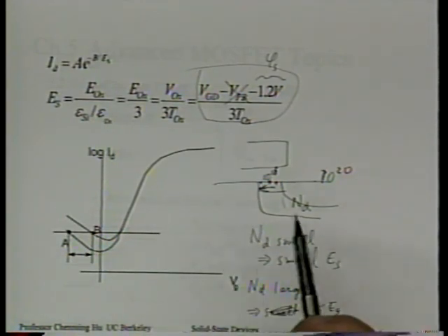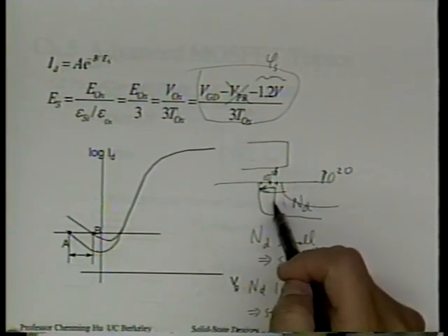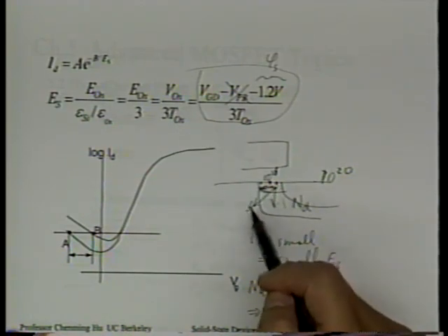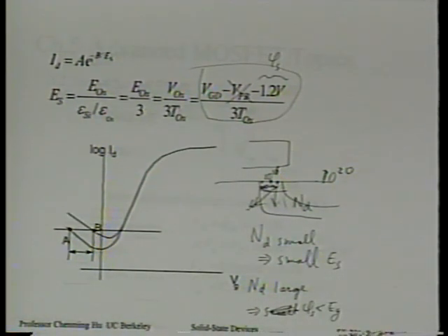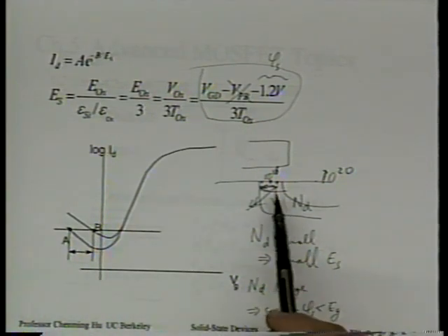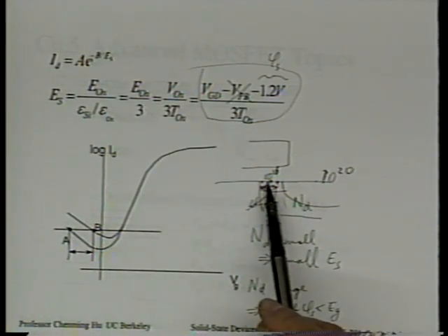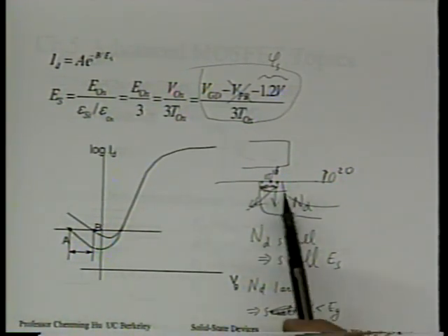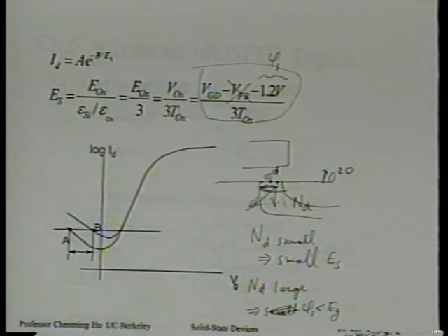And tunneling happens, doesn't matter which direction the field is. Vertical field, horizontal field, the carriers will just tunnel in the direction of the total field. So it's known that we cannot tolerate, for example, a very sharp, just arsenic junction. If we do that, GIDL is more severe, and we like to have more graded junctions, so LDD tends to help with the GIDL as well, just by suppressing this lateral field.